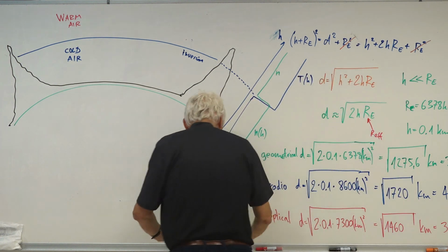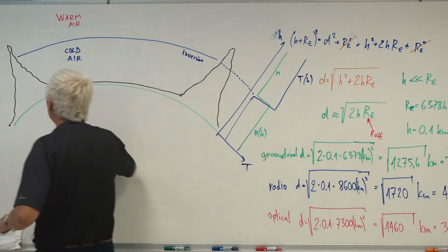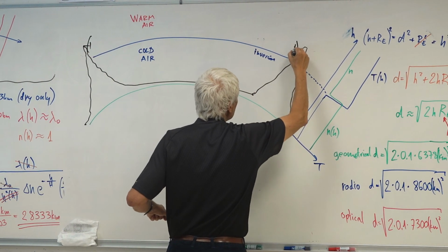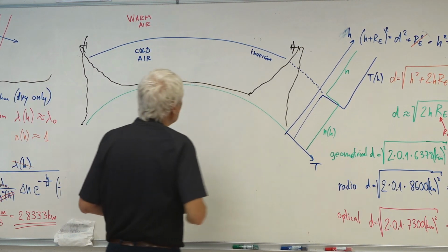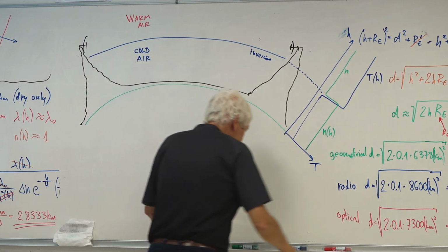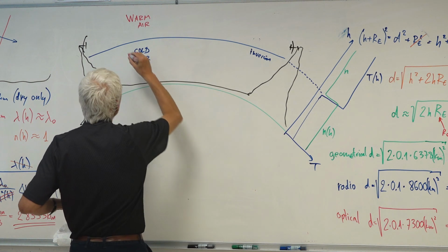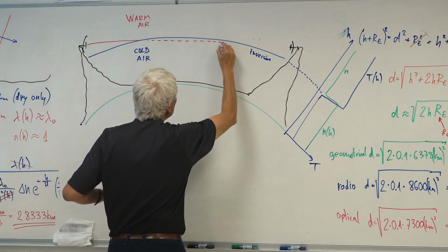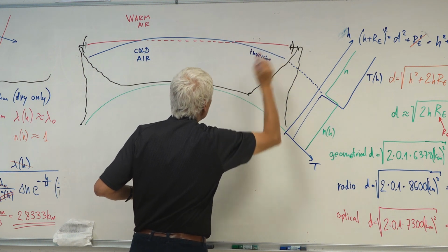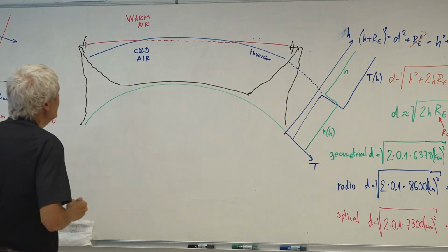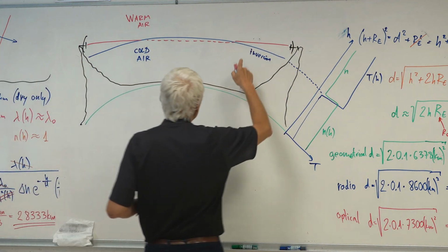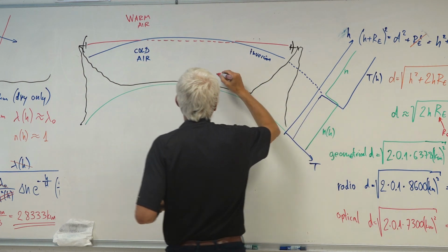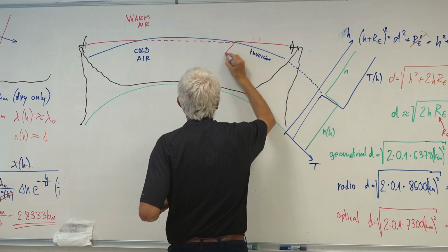What may happen now for my radio link? Before, I had a radio link between two mountain tops, a microwave directional link with directional antennas, and this link was following this track here, going partially through the inversion layer and ending up in the end antenna. Now, on the inversion layer, I have a jump of the refraction index. In a larger refraction index, I get refraction down here.